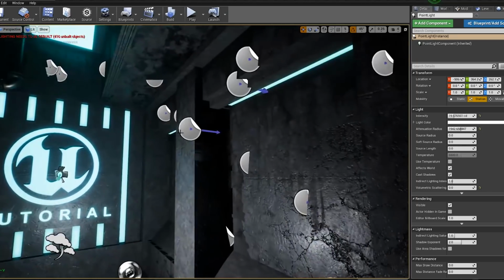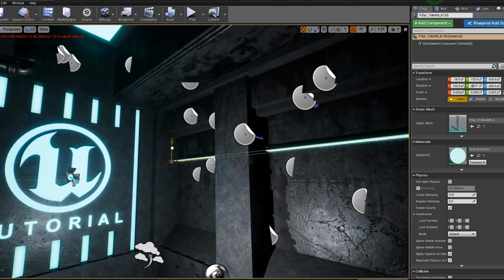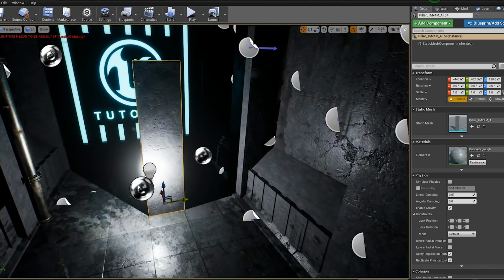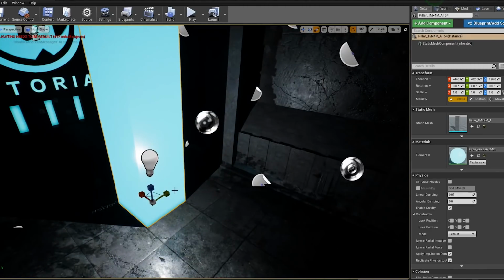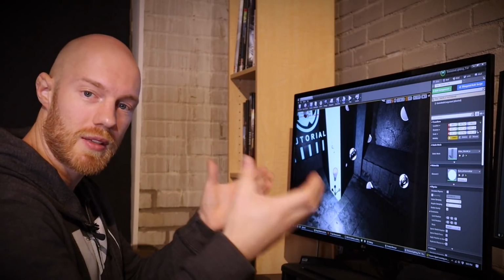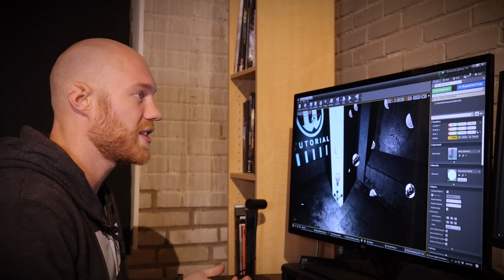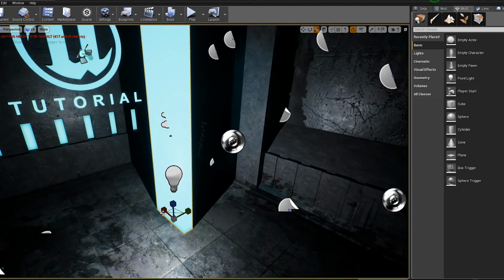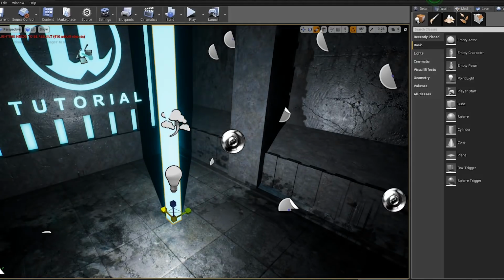But all of these strip lights are just geometry. In fact, it's actually this pillar. What I did is I duplicated the pillar, slapped on the emissive material, and then just scaled it. For using emissive materials, unless you're using a texture to simulate neons or some type of gradient inside the light, or the light fixture cover itself, you don't really need UVs. So you can just grab even a basic cube from here and slap an emissive material on it, and you're pretty good to go.